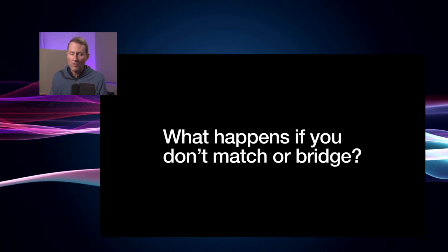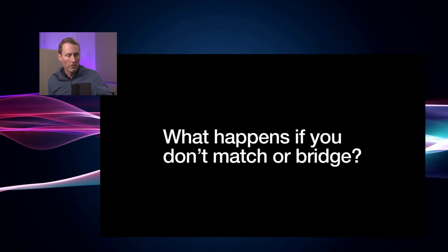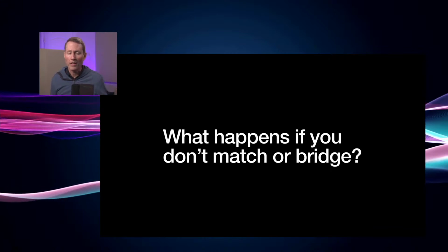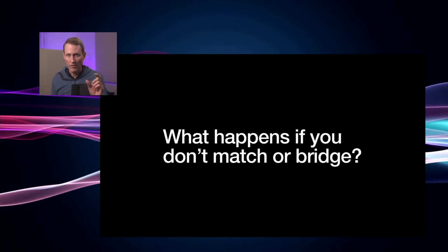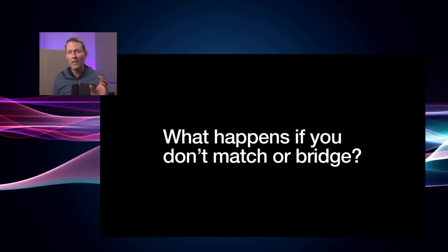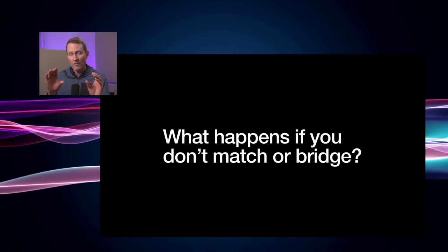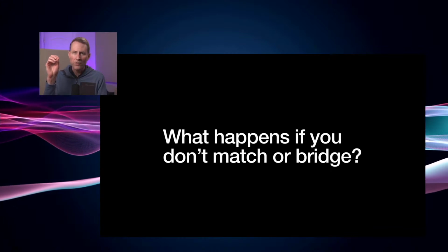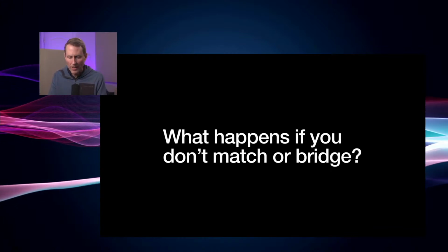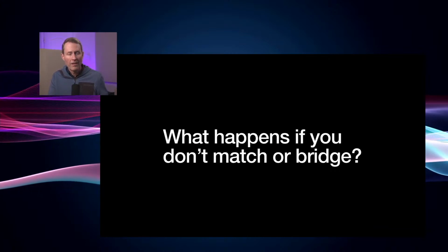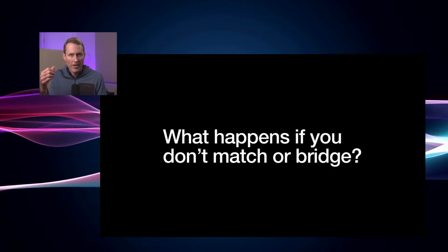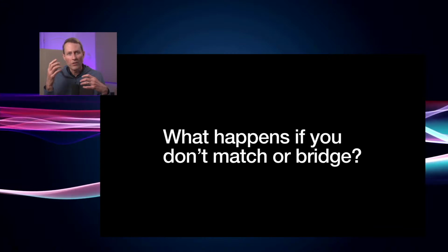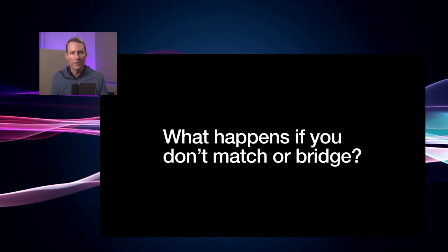And in fact, there are some pieces of gear today, for example the Universal Audio Apollo series of audio interfaces, that have a feature where they can change the input impedance on the microphone inputs. They do that intentionally so that they can mimic some of the vintage gear that they have plugins for. So if you have a Unison preamp of some sort for your Apollo, and you're trying to mimic, say, a Universal Audio 610 microphone preamplifier, then it matches the input impedance on your Apollo so that they can do a very good mimic of that original analog gear.